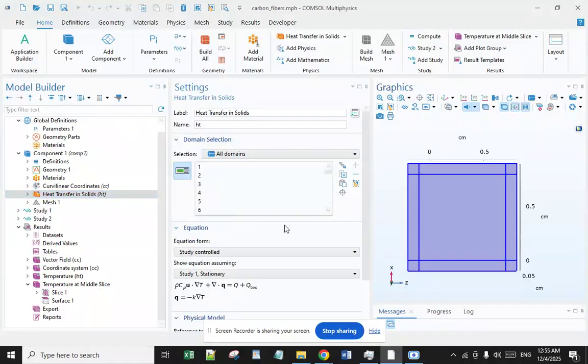And what about the results and discussion? Results of the specific heat capacity. Here in this simulation are the results of the DSC experiments in the form of specific heat capacity C_p as a function of temperature. The results clearly show an almost linear relationship of the specific heat capacity as a function of temperature for most parts of each curve.